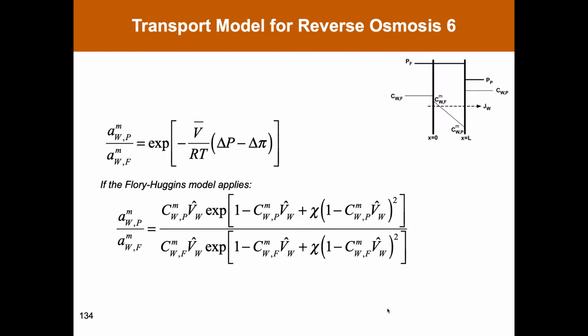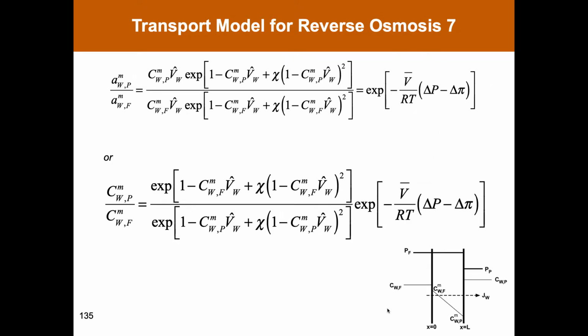And again, what we're after here is to be able to relate experimentally measured variables like the pressure and concentration of solute in the external solutions, to a concentration gradient in the solvent in the membrane that we really can't measure. And it is that concentration gradient that is driving the transport of solvent through the membrane. And so we have to be able to relate the internal concentration gradient with the external measurable parameters, and we do that through this thermodynamic analysis.